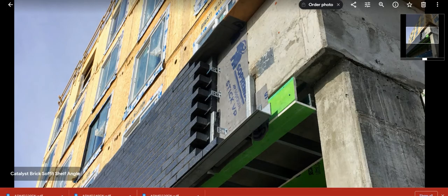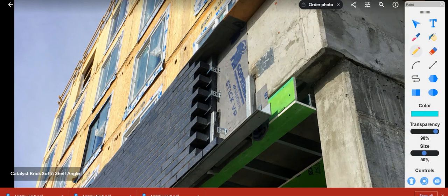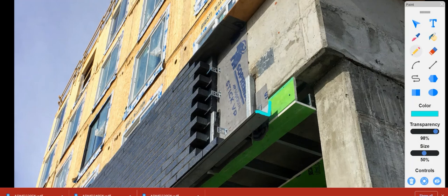And what that looks like in real life. Again, not the same building, but there it is right there. There's the edge of that steel angle, and there's the brick resting on that steel angle. The steel angle is going to carry the loads back to the superstructure. In this case, here's the steel angle right here, and it was below the actual concrete of the superstructure, so they need to attach it back to the superstructure. They've put a weld plate vertically in this building and put a small HSS tube welded to that weld plate, extending down, and then this angle is welded to that.